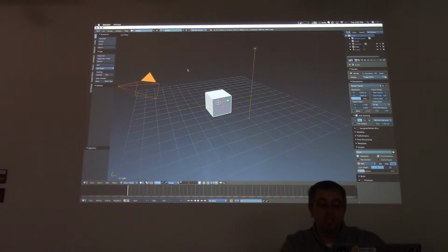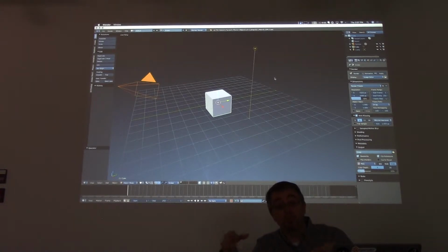So the very first thing that we need to do, and this is really something that you want to do with 3D printing or CNC milling, anything where you're trying to make this a physical thing later, is you want to go ahead and set up the units. Because by default, Blender operates in Blender units, which isn't that unusual because 3D software doesn't really care about whether it's inches or millimeters, because you're just making 3D things in a 3D world, and it's kind of irrelevant. But since we're going to make this 3D stuff into the real world, we do need units.